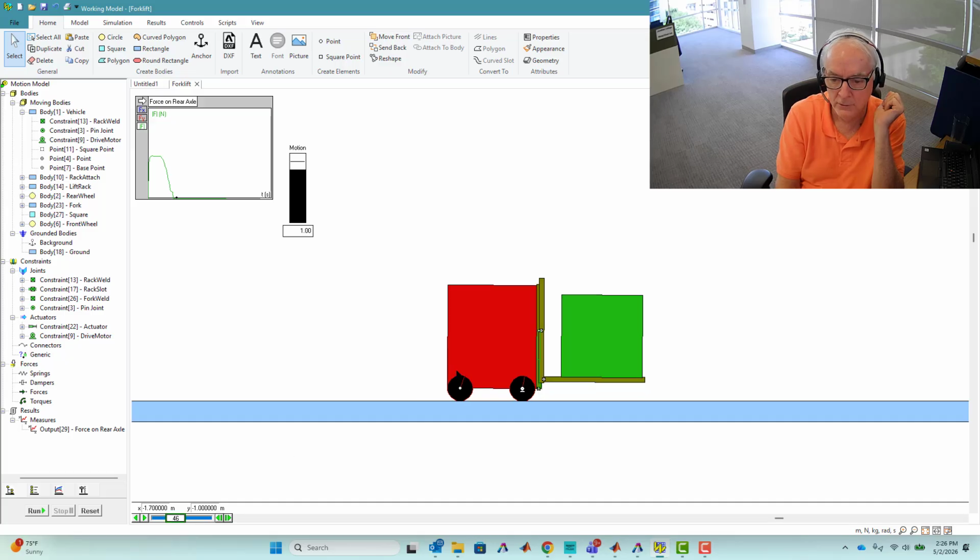And so we'll do some work on the Simulink side. We'll measure that force and make sure we recognize when it's transitioning from a positive value to zero. In reality, it will go to zero. But because we're modeling it as a connected constraint, which is connecting that vehicle to our motion platform, we'll see it go negative. But in a way we don't care because we know the condition that would lead to tip, and that's what we're observing in that figure right there.